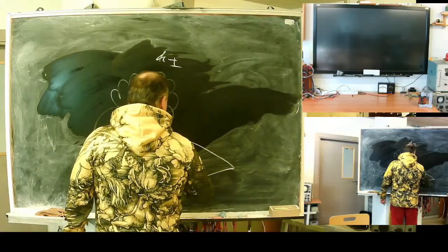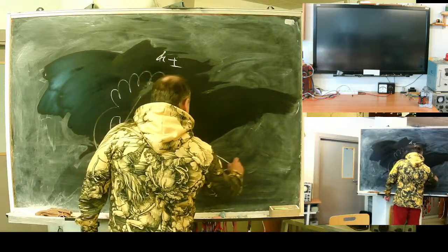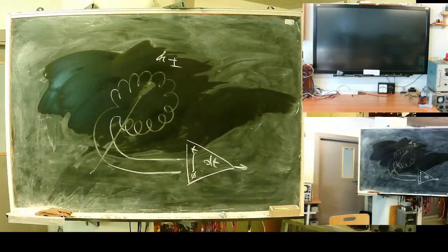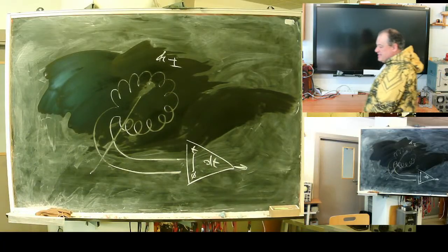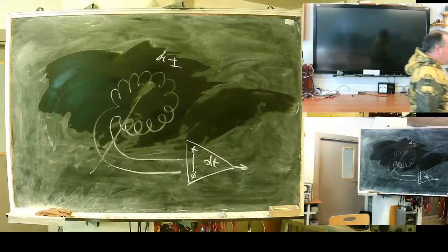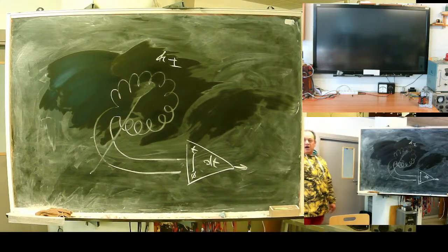You need an integrating part somewhere inside your processing chain to get current, because it produces a derivative, not current, not something proportional to current, but something proportional to the current derivative.